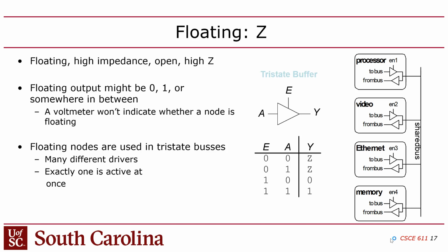There's no way that it can signal to the user that you've double driven a signal and you've got contention. And the reason it doesn't do that is for performance. Verilator is designed for performance, to be fast. So this is a trade-off, a compromise they make. They don't allow you to have 4-state logic.